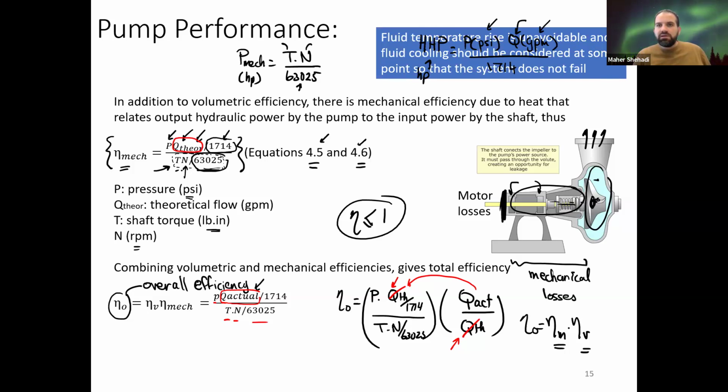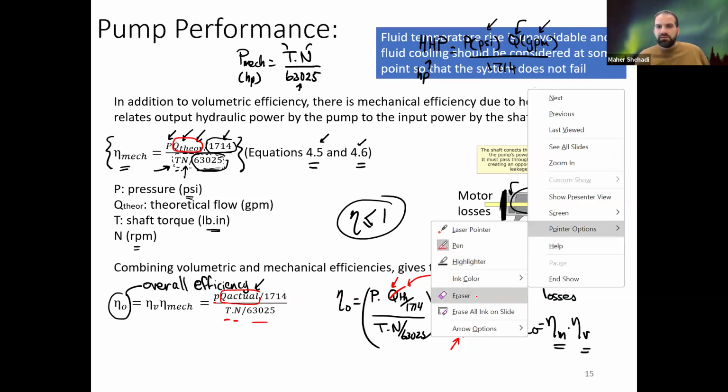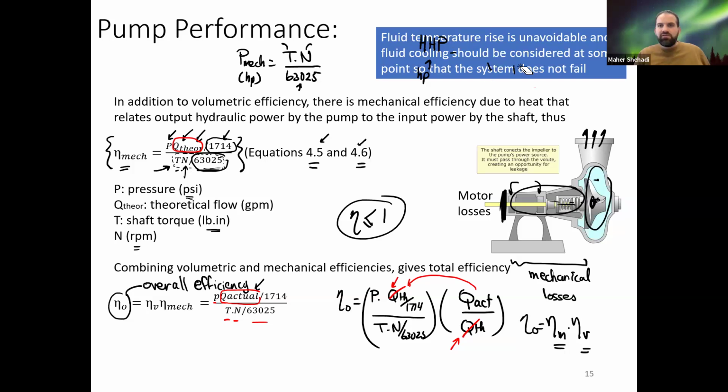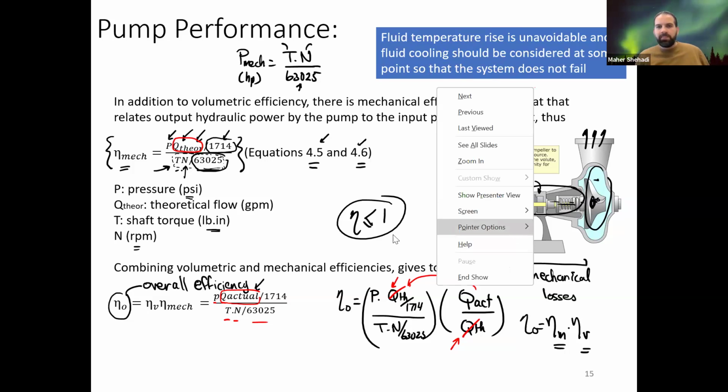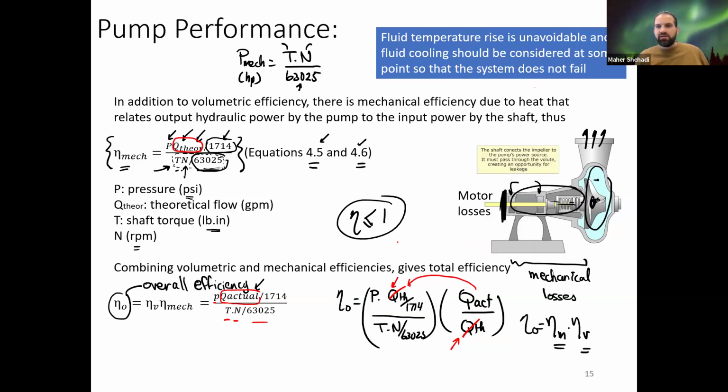Another note here. Fluid temperature is also something that you need to consider when you're working with hydraulic fluid. It's unavoidable due to friction, it's going to heat up. So if you do a performance test, when you start the pump, it would be different than after running the pump for 2 hours, 14 hours, and so on. Also, we mentioned that when we did the labs for the pumps. Do you recall we used to record the temperature before and after?